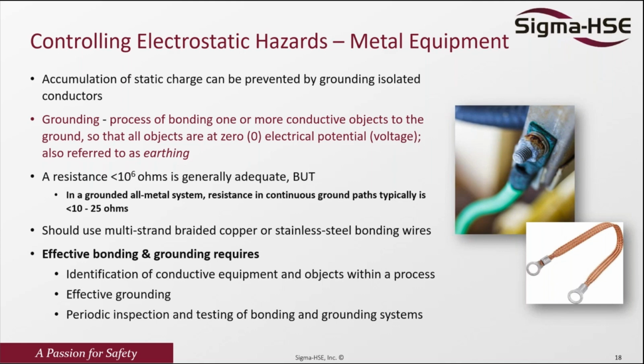This is something that I see a lot. I've been to industries where operators go to equipment, do some maintenance, remove the grounding strip, and after that they forget it. I also investigated an incident where there was a fire where the person filling a tank forgot to reconnect the grounding cable. That is something that needs to be addressed in the industry. This is the killer side of everything: forgetting or not inspecting, rather than ensuring that everything is intact before starting any kind of operation.